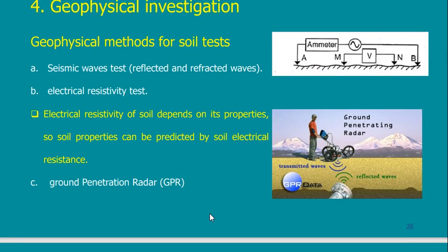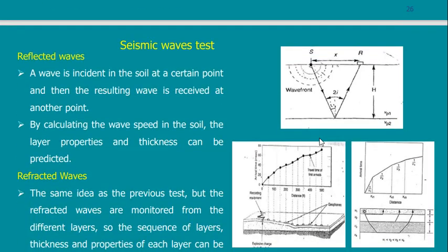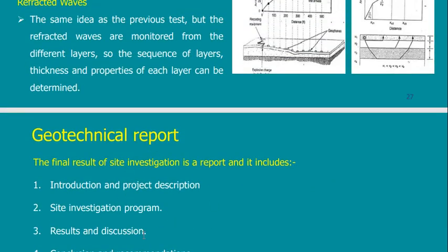that you may have done for yourself at any physician. It's the same, it's an equipment, you just pass it on the ground and try to send a wave and analyze the returning wave to check what is the type of the soil and the depth of the soil below. And then finally we present all in a geotechnical report showing us what is the formation of the soil in this site and what is the layering and what are the soil parameters and so on.